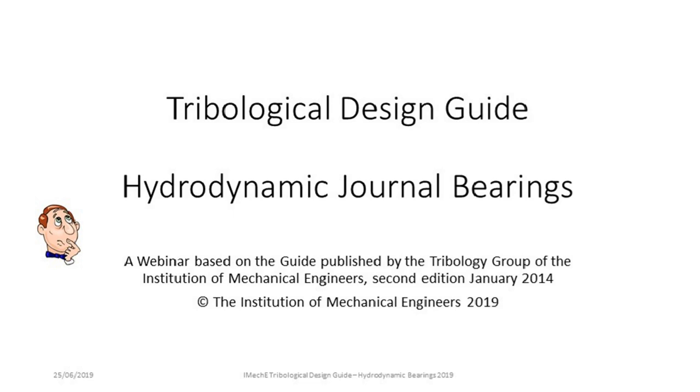Okay, well, the key thing, of course, in any lubricated bearing, is to make certain that the solid surfaces don't come into contact. And the limit of 4 megapascals, or that sort of number, using conventional materials and conventional hydrocarbon lubricants, is a rough guide to that requirement. It's not a hard and fast rule, but it's a sort of first rough calculation to see if you're in the right ballpark.